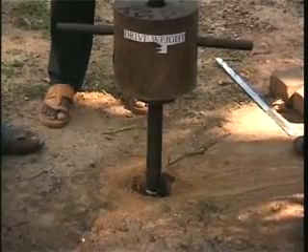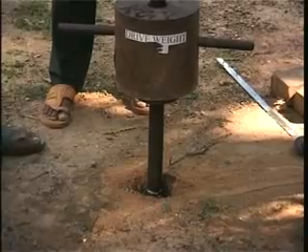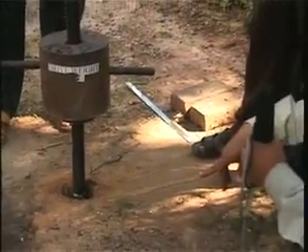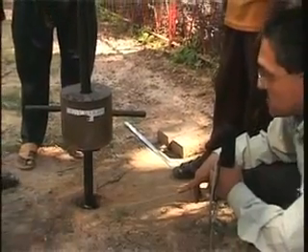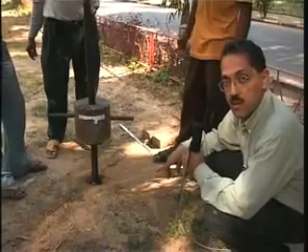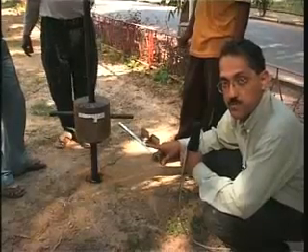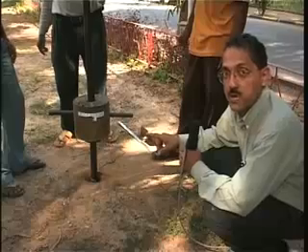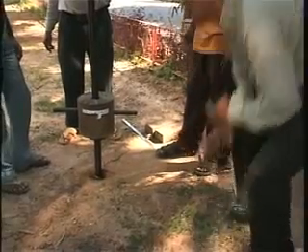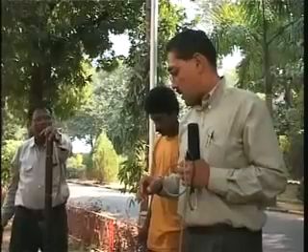So in this particular case, the raw SPT blow count is recorded as the total number of blows required for the penetration of the second and the third 150 millimeter, which is 3. So the uncorrected SPT blow count is 3. Okay, so that's the demonstration of the standard penetration testing, and we are going to move on to the next demonstration now.